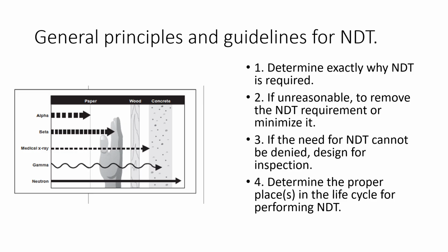How often are we going to look at these parts with non-destructive testing to determine whether they need replacement or repair, or the whole thing needs to be scrapped? So this is some of the guidelines that go into non-destructive testing and figuring out how often we're going to do said non-destructive testing.